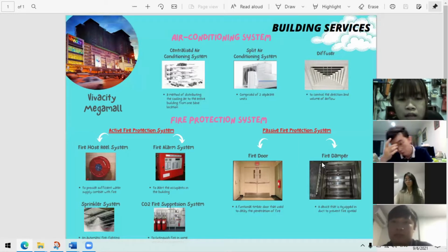The cycle of the refrigerant in this plant is that the low pressure refrigerant in gas form will enter the compressor and be compressed to become high pressure. Next, it will move to the condenser. Through the condenser, it will become high pressure refrigerant in liquid form. After that, it becomes low pressure when it passes through the expansion valve. Due to the lower pressure, the temperature of the liquid also drops and becomes cooler. Lastly, it will flow through the evaporator.